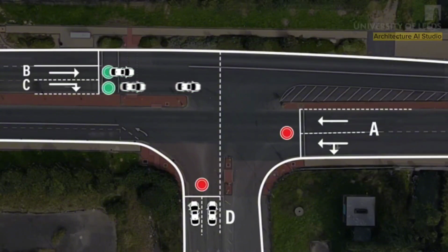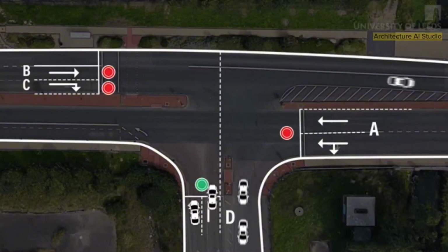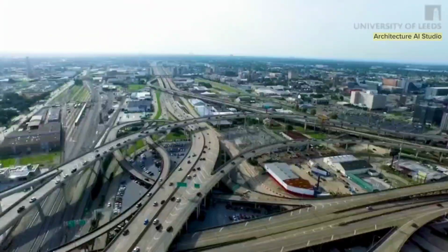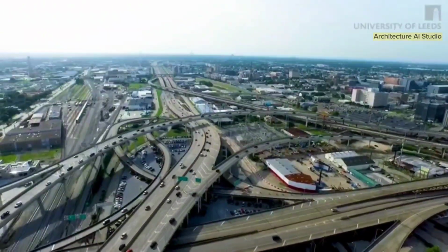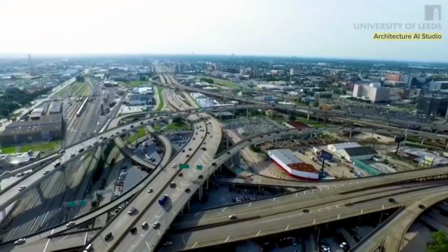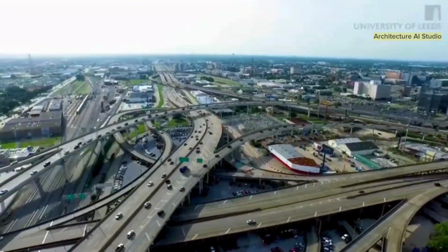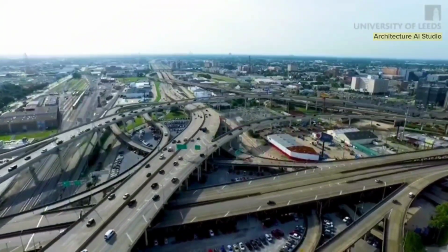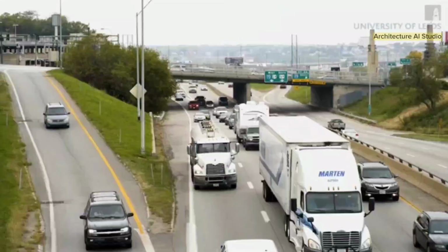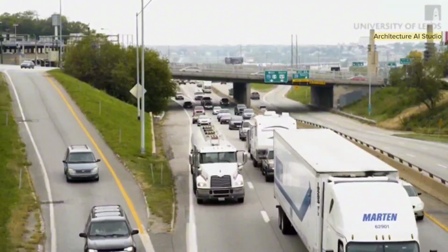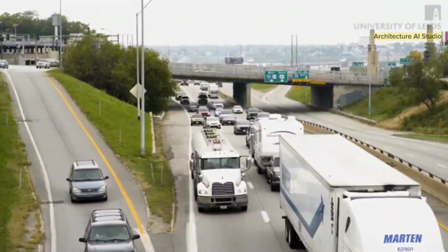This example illustrates how each stage in the light sequence manages the flow of traffic as a single-lane road meets a two-way carriageway. Grade-separated junctions are intersections where one road passes over another, with or without ramps to connect them. They are designed to allow traffic to move more freely, with fewer interruptions and at higher speeds. They also provide fewer conflicts between traffic flows, reducing the risk of accidents.